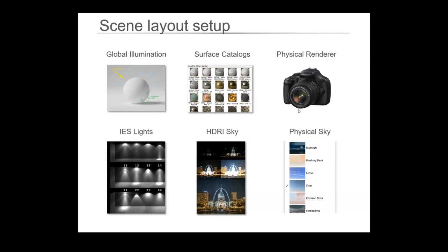What rendering tool you're going to use is another thing. Like in ArchiCAD itself, if you want to render out of ArchiCAD, you need to build the model up to a greater level to be able to produce nice images. But if you're going to use one of the rendering add-ons like Enscape or Twinmotion, whatever, Atlantis, you can just take a basic ArchiCAD model and do a lot of the touching up in the rendering engine.